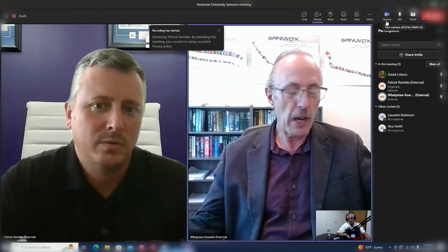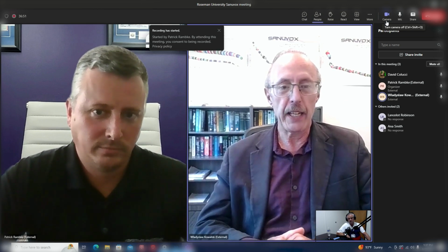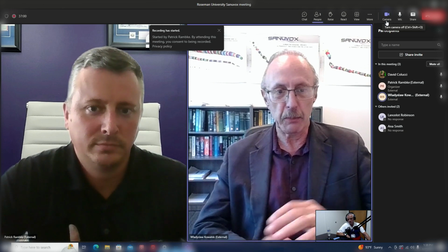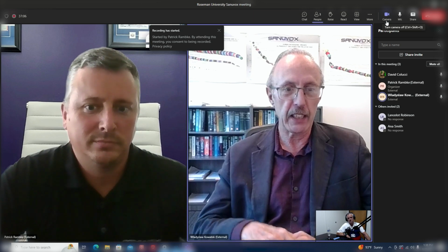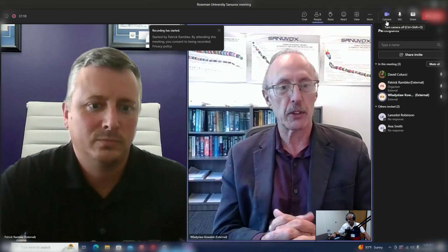So you have to size the system exactly such that any ozone produced is consumed by available VOCs and odors. If you have a lot of people or foods in a room, you're continuously producing VOCs, and any ozone produced by, say, a medium pressure lamp will be consumed in time, and you won't measure any actual ozone. So these types of systems also have to be engineered precisely for any individual application. But the option exists for removing all kinds of VOCs, especially when we use far UV or medium pressure lamps, which produce ozone.